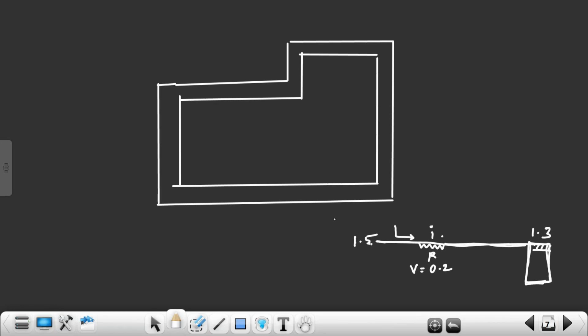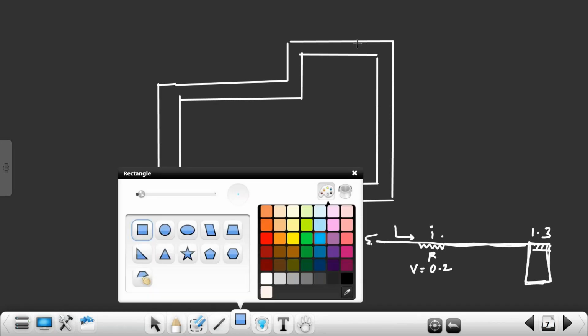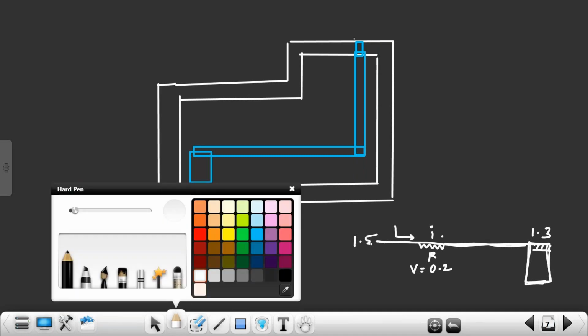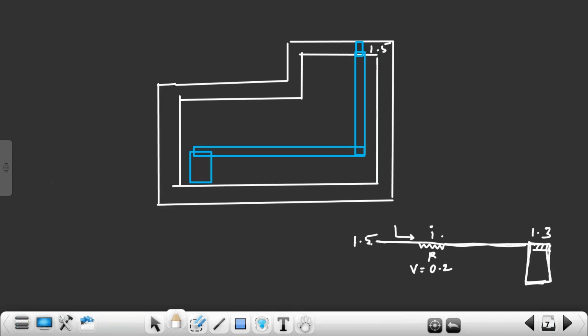In this example, I have a VDD port here and a standard cell is present here. I have to connect from here to here, so this much metal length. More metal length, more IR drop. Here I have 1.5 volts VDD. In lower technology, VDD is very small. In UG, you would have studied VDD as 5 volts or 12 volts. But in lower technologies like 28 nanometer or 14 nanometer, VDD is only 1.5 volt.